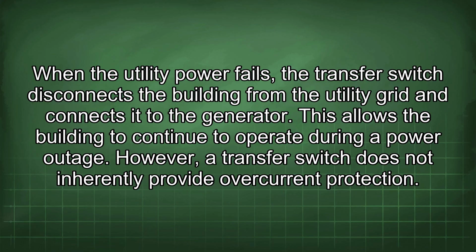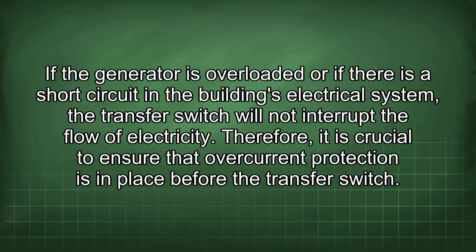However, a transfer switch does not inherently provide overcurrent protection. If the generator is overloaded or if there is a short circuit in the building's electrical system, the transfer switch will not interrupt the flow of electricity. Therefore, it is crucial to ensure that overcurrent protection is in place before the transfer switch.